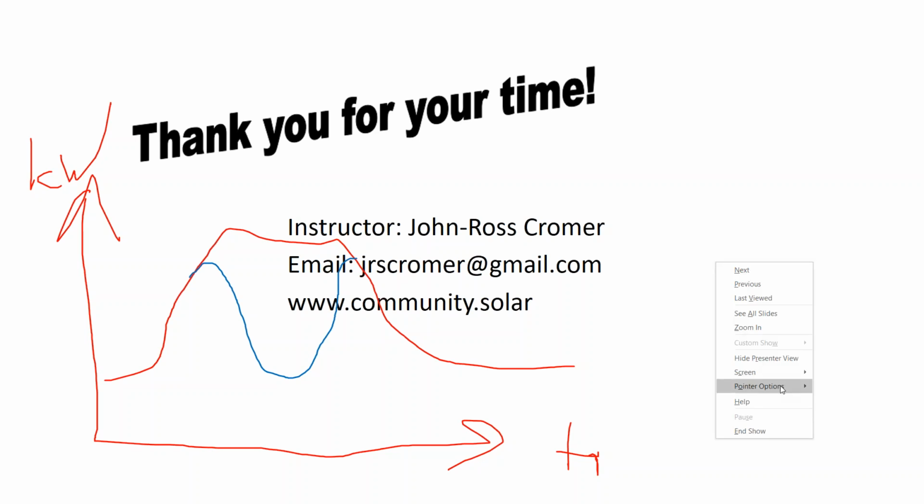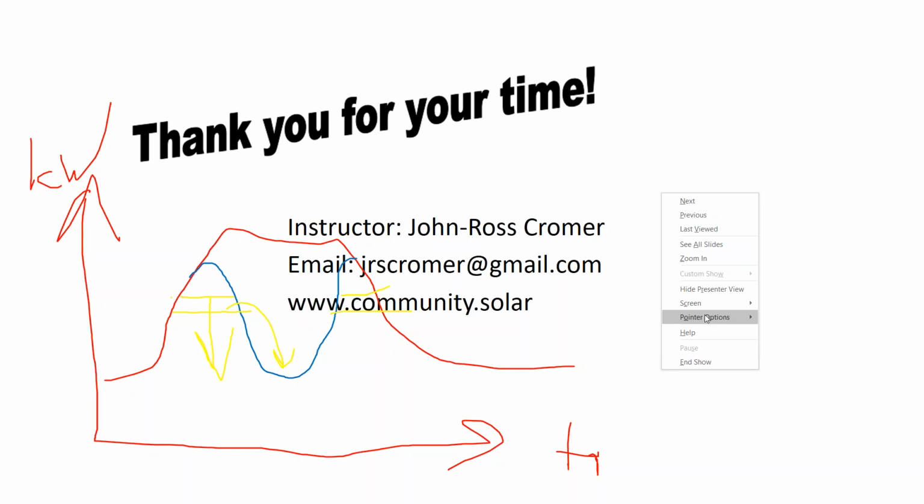And then a battery bank can come on and provide us with some additional load leveling, but then you get into diminishing returns the further down this curve you go. Maybe we can do some additional load shifting to put some of this into here to get that demand management down even a little bit further. But eventually, all we're doing is smoothing out our building performance, but you're always going to be left with these valleys.